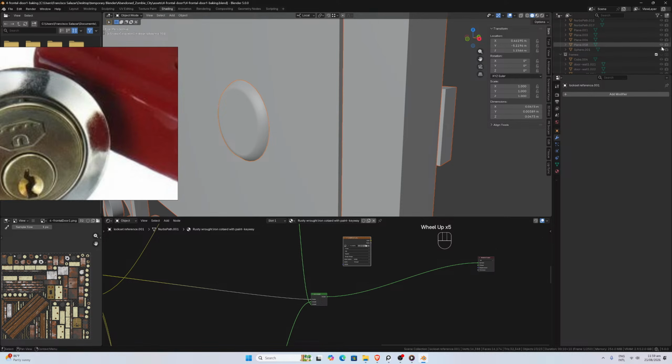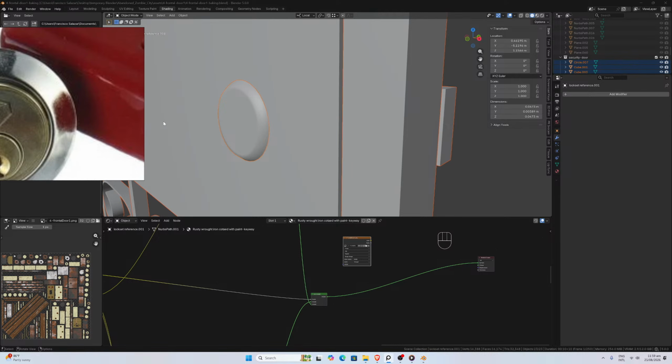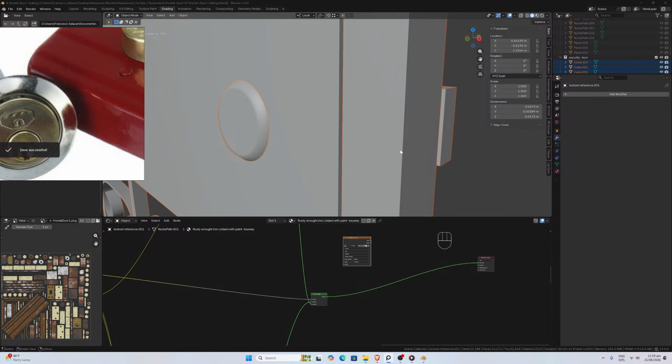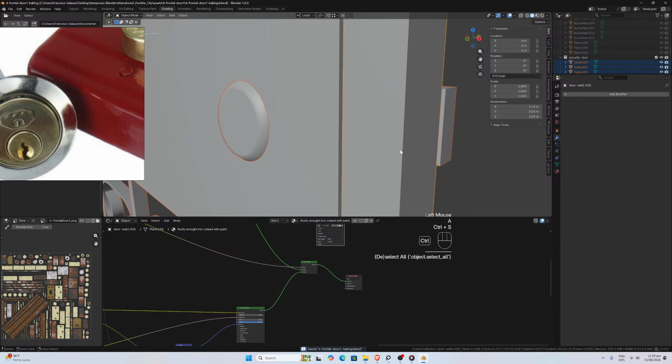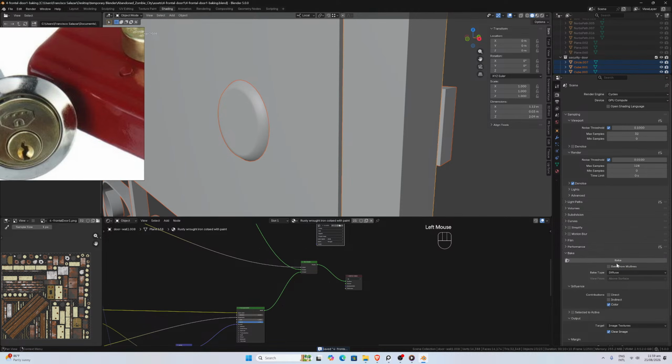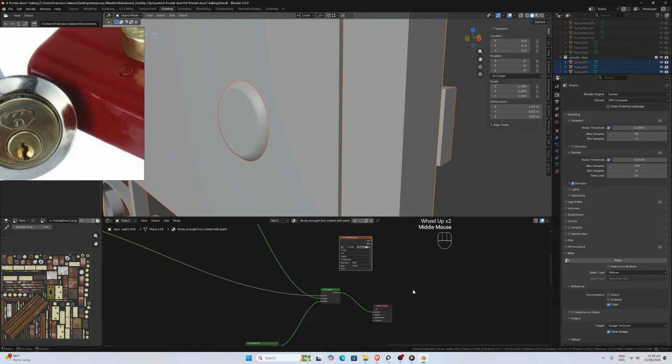We have all the other turned off and also the render turned off. And here we have everything turned on. Perfect. Now let's see if this is going to work. A lot of work. And press bake. We're going to start with the diffuse, always with the diffuse, to see the level of detail. Bake. Now we have to wait a moment until the PC completes the baking process.